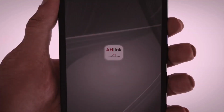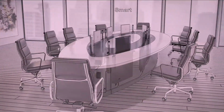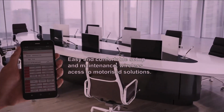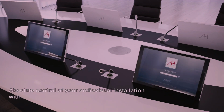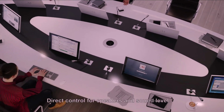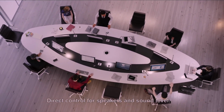So when we are looping our devices for control using the AH Link, we are doing that on Cat6 cables. Earlier we talked about Cat5 cables for this, but due to all the wireless getting into the more boardrooms and so on from different devices, also what we're bringing ourselves, we recommend a shielded cable or Cat6 cables. And when we are looping the devices for control, we can actually loop between screens, retractable cables, retractable microphones, and retractable speakers. And then we can still individually control them.